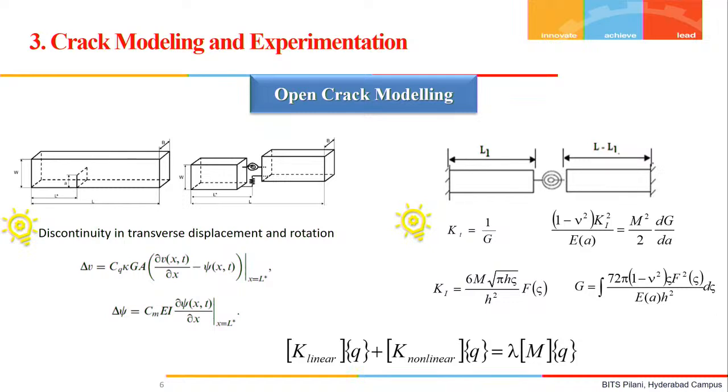Furthermore, we have also found that for the system's total strain energy after considering the springs, the coupling can be neglected because the influence of shear, in particular in the open crack, is very negligible compared to the opening mode, the first mode. So if we model it by a rotational spring, then as I told, remaining in the framework of the linear elastic fracture mechanics and without considering the crack growth also, several beautiful outputs can be taken out for the structural engineers. That is what we are seeing.